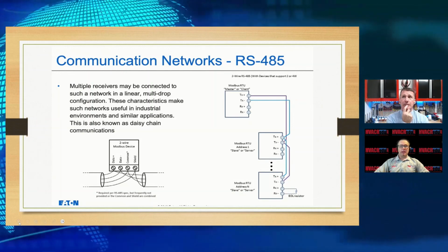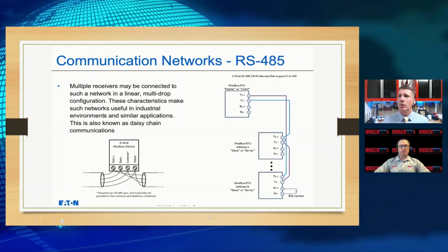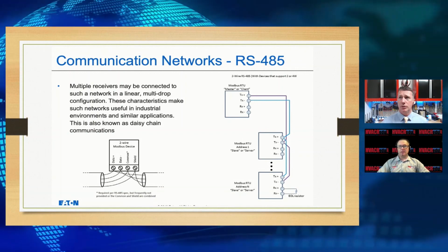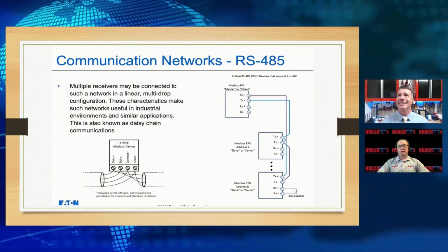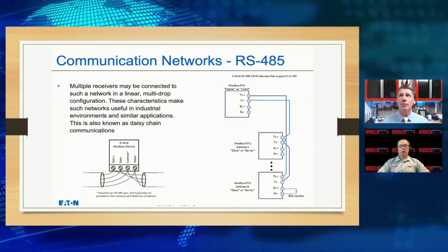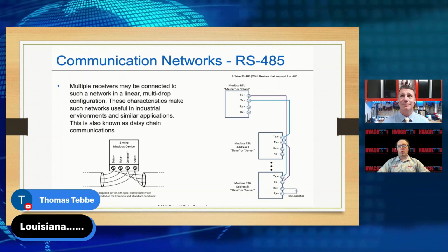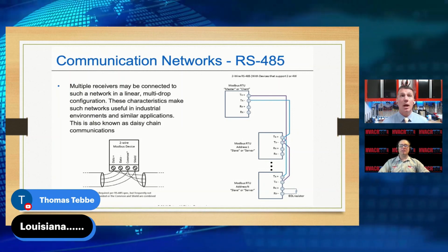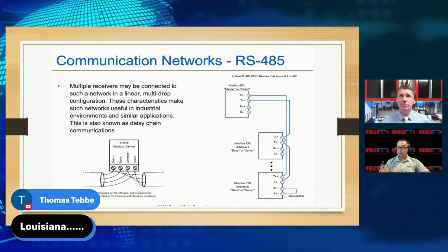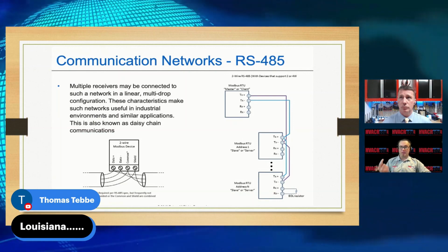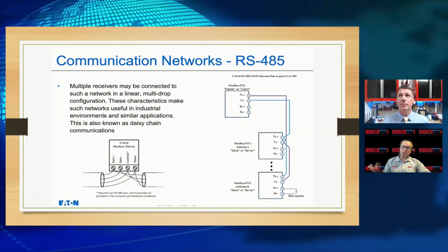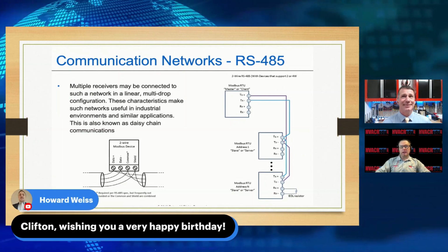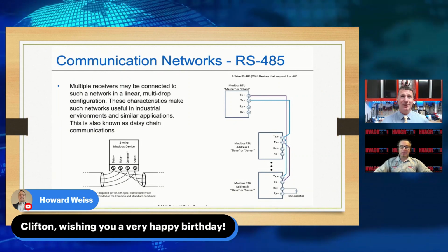Absolutely. And so in that communication, we have a master-slave type application, very similar to the RS-485 cabling that we are used to. Usually a four-wire lead wire, usually two for communication and two for voltage to power the device. Usually 12 volts, maybe sometimes 24, depending on the device, and then a common, right? You've got to make that complete circuit.